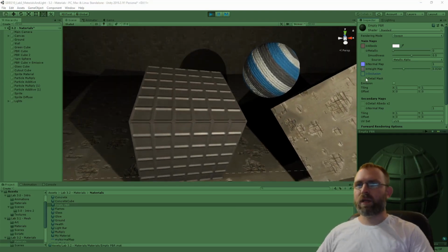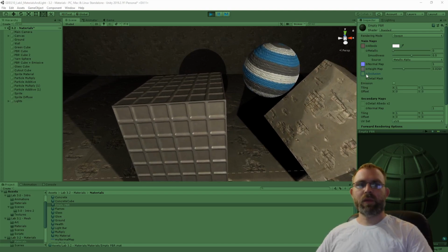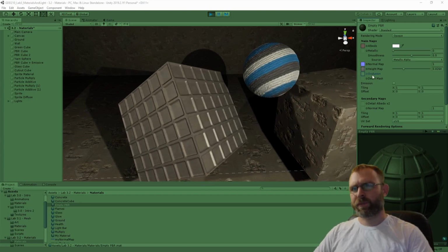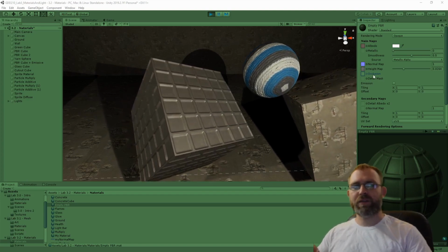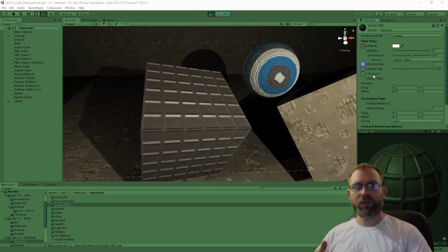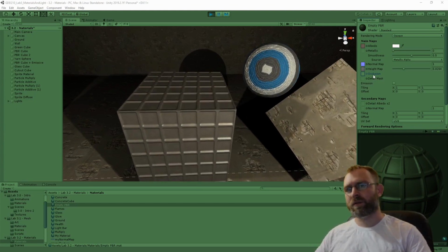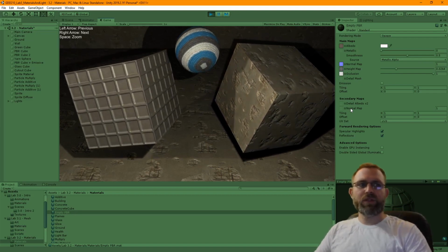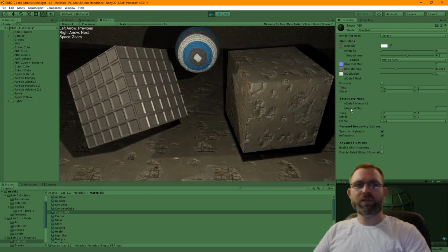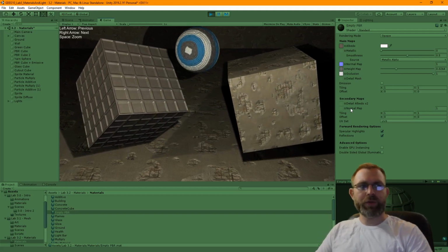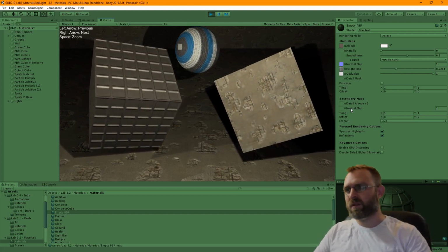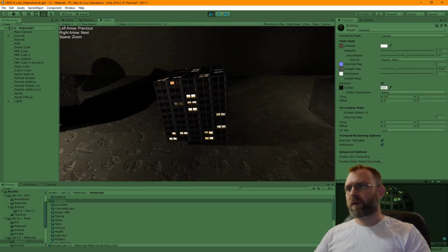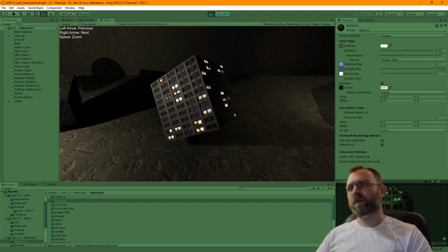The next field we're going to look at is the ambient occlusion field. This texture map defines how much ambient light an area should be exposed to. So for example, deep cracks in a material that would receive less ambient light should therefore appear darker than the surrounding areas. Okay, using these maps should be enough to get you started on working with realistic looking materials. All the textures I used in this project were found on textures.com, where you can find free to use PBR ready textures like these.